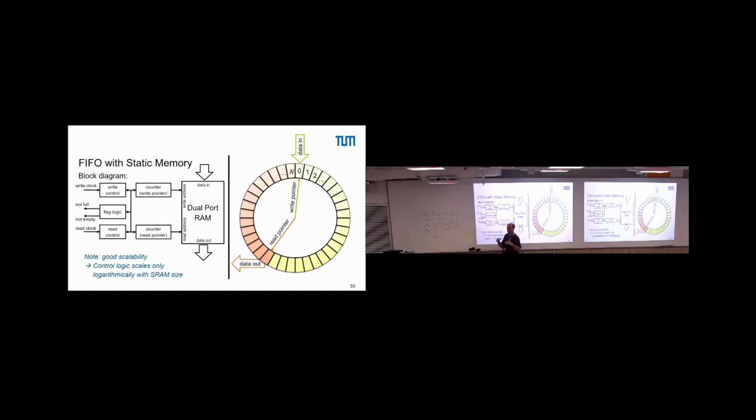Maybe a step back to once again explain what the actual problem is with these asynchronous things. You remember we said if we have latches between our logic, then we would have to consider the complete timing. Why is this? Because we do not have enough information at design time about the individual intermediate steps.